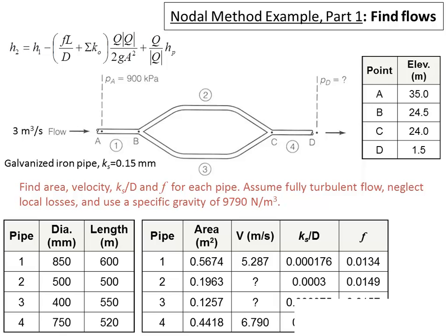What was the other assumption that all of this hinged on so far? Yeah, we invoked the fully turbulent flow assumption. And so what we need to do now that we've got this velocity is find the Reynolds number, and with the Reynolds number, go back to the full version of the Colebrook equation to make sure that that's valid.